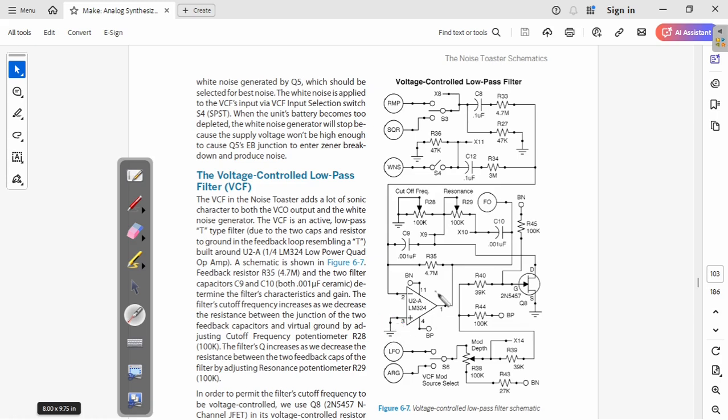Here I say ground, but in reality it's a virtual ground, because in the schematics the virtual ground is actually 4.5 volts, so half the supply voltage, so be careful about that. In my case, I'm going to consider it a true ground. So it changes things a little bit, but I think it's easier to understand.